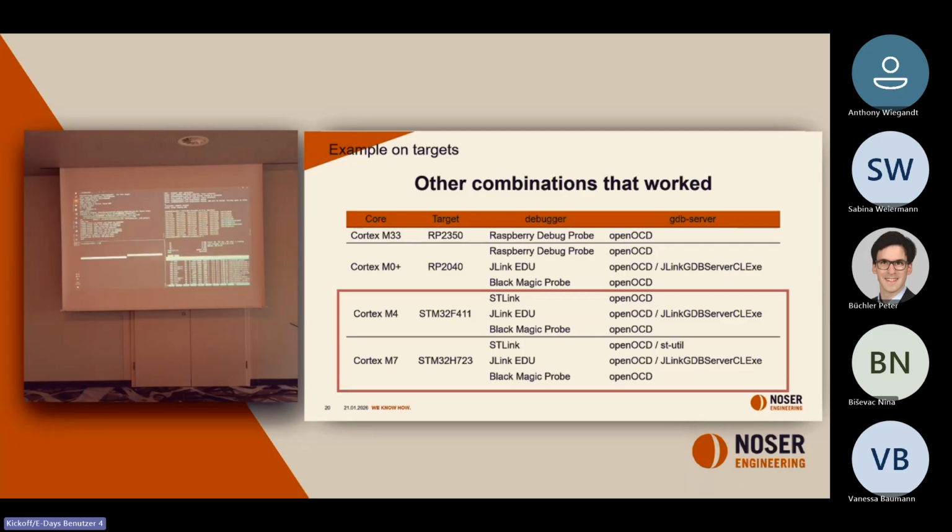It's ready. We can also start minicom again. Minicom -D /dev/tty, and here just run. Starting again. And here you actually have no need for your target, because the GDB server is working on this small piece here.